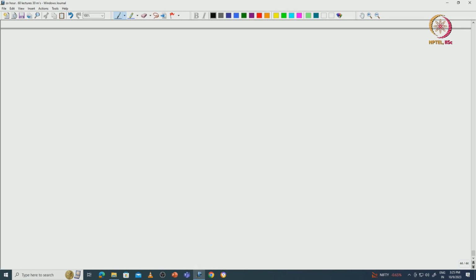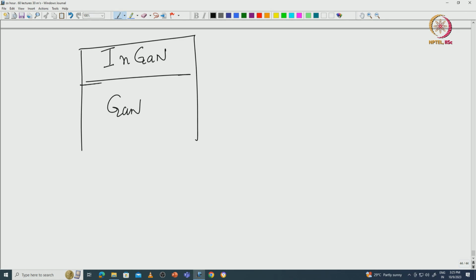So, in the last lecture we talked about AlN-GaN. Now, we are in a position to go back and see if InGaN-GaN will give a 2D electron gas. Will it give a 2D electron gas? No, it will not. Why? If you recall what I talked about in the last lecture, gallium nitride has a negative polarization charge here; the bottom you can ignore. InGaN has negative at the top, spontaneous, and positive spontaneous at the bottom. Now, the spontaneous charge of InGaN is not very different from that of GaN. So, these quantities are not exactly going to cancel each other, but more or less close.